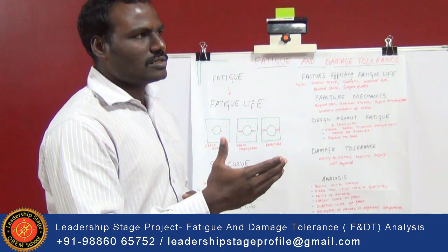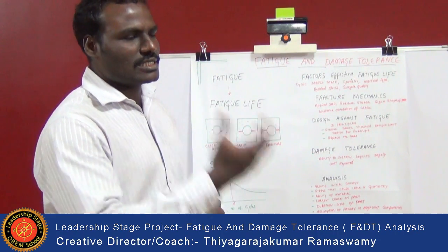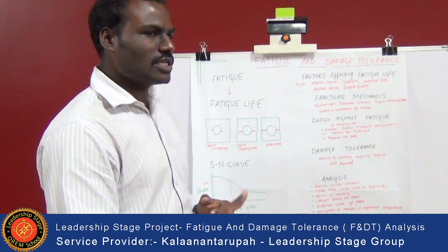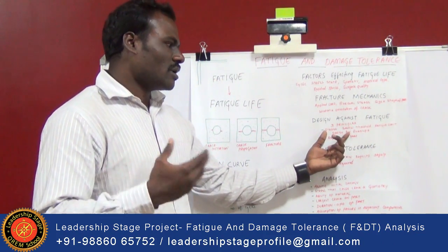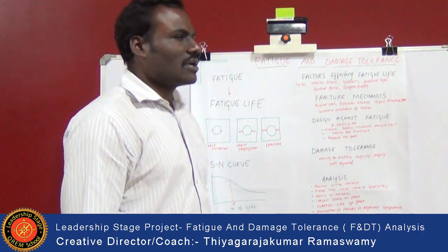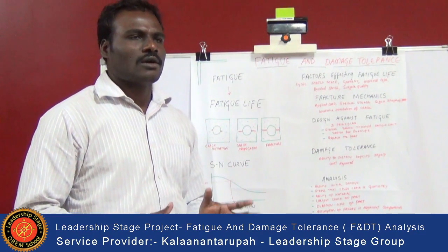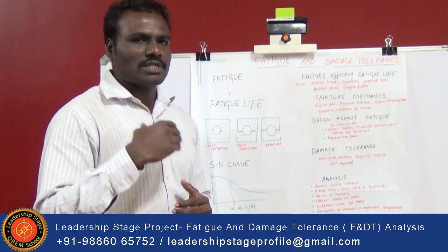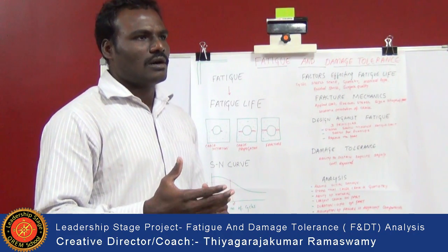will be sustained up to its elastic limit due to the applied load. If it exceeds its limit, it does not regain its original position, which leads to a fracture. So we need to apply the load within the threshold fatigue limit. Then next we are going to design the fixed life. Some of the manufacturers, while manufacturing the component itself, specify the actual life of the component, so that if you involve this component in mechanical activities beyond that, this will lead to a fracture.